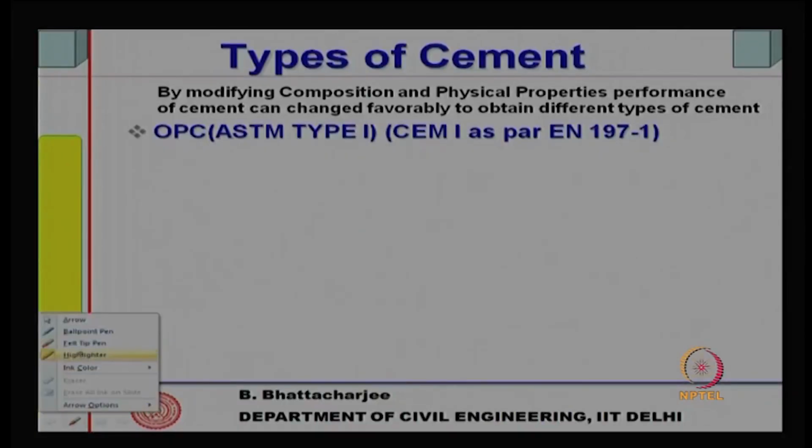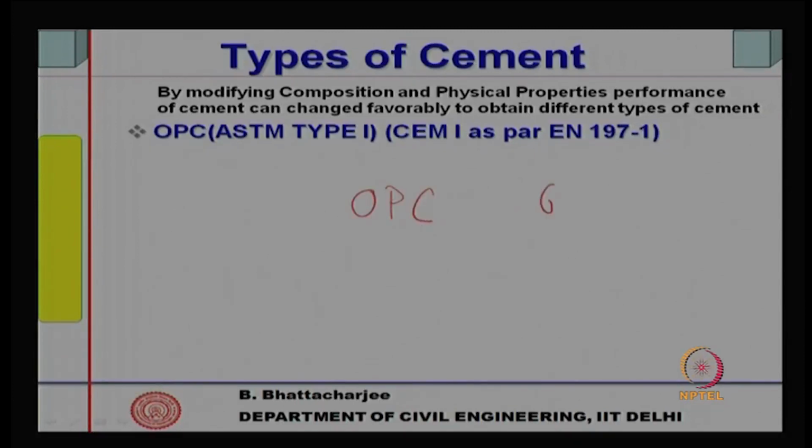In Indian standard, IS 269 deals with 33 grade of OPC cement, and other cements like 43 and 53 grade, which are classifications by Indian standard. They are OPC, also called OPC grades. So, OPC is IS 269, they are called OPC cement simply. Now, this is specific to the Indian scenario. We talk of OPC grades 33, 43 and 53.